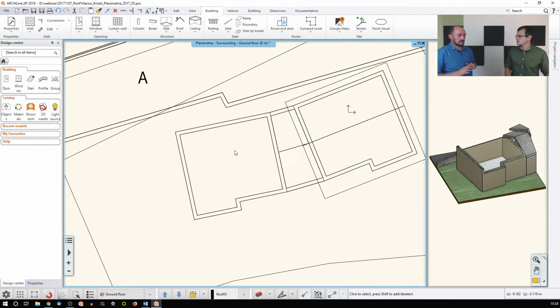I will cover that pretty soon, but there is the other way, when I just go to the spot and measure the wall and the ceiling. That way I know that in the corner the roof was, I don't know, 2.4, and here it was only 1 meter. If I know 3 heights of a roof, then the software can draft me a roof plane. So if my job is to design only two roof planes, then I don't have to use the big cannon, the automatic roof or something like that. I just use two roof planes and that will do. Then you can do it by plane, and actually this is a very good solution for attic spaces, because that way you can build it up one by one. So let's see how that works.